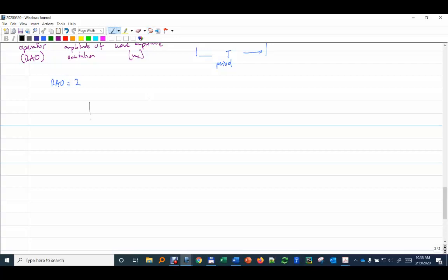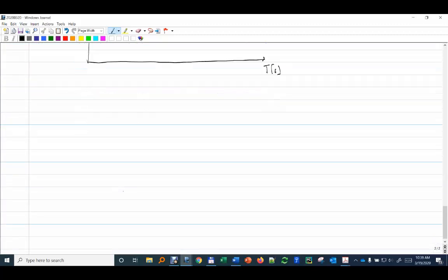Okay, so we make a plot of this rho, which is a dimensionless number, but we put the units here versus period. Or we can also use frequency, but we use period in seconds. And we see how the response of a given structure behaves. I'm going to show you just some plots that I took from some books and some theses.